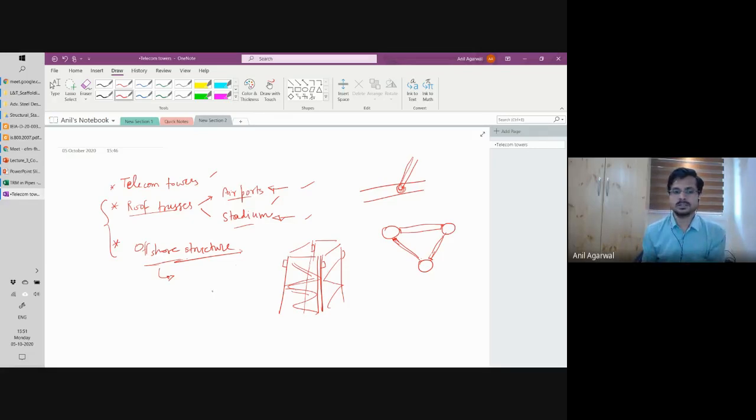But funny thing is that if you calculate the area of steel versus the hollow area inside, you will see that the hollow area inside is 7-8 times greater than the steel area, which basically means that if you have water pressure acting on this from all sides, it will float. The steel pipe will float as long as water does not get inside. If you have air inside, then the pipe will float in water. They need to take it to the offshore location, which may be 20 or 30 kilometers deep into the ocean, away from the shore.